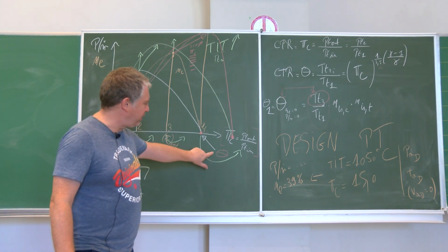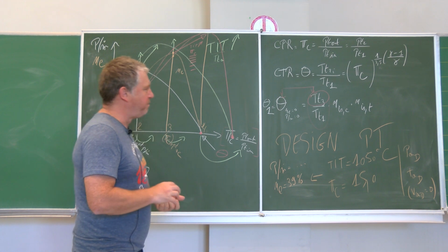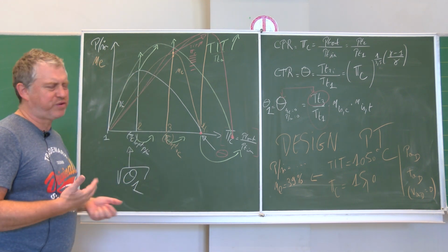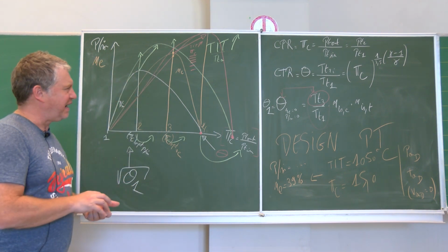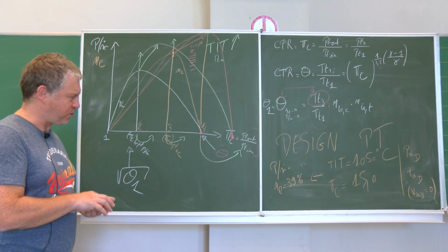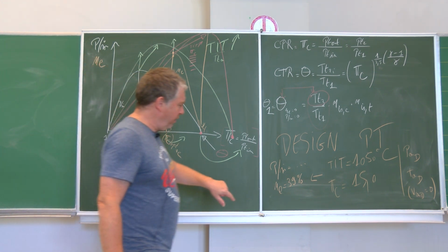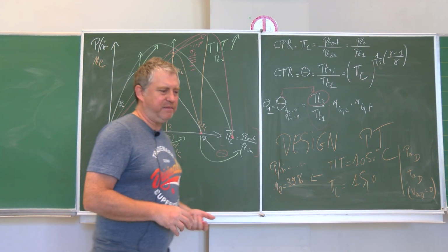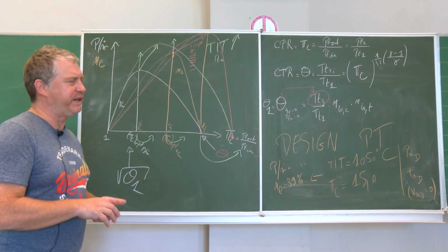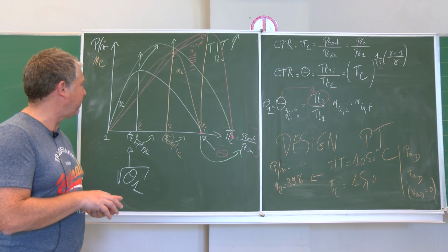And so you see that for discussion, working in compressor temperature ratio, theta is a bit useful, even if this parameter will not be so often used in this course. Okay? And eta E, let's say, just lower than 40% is already a quite good one.